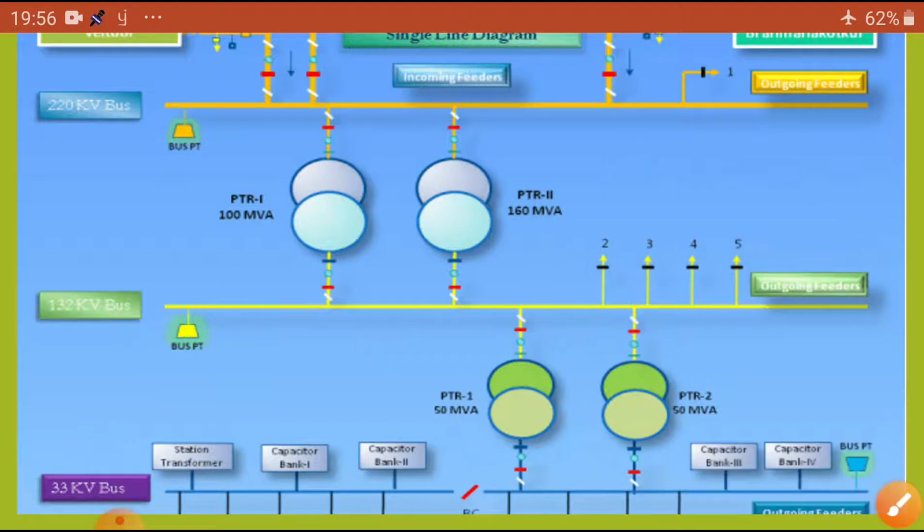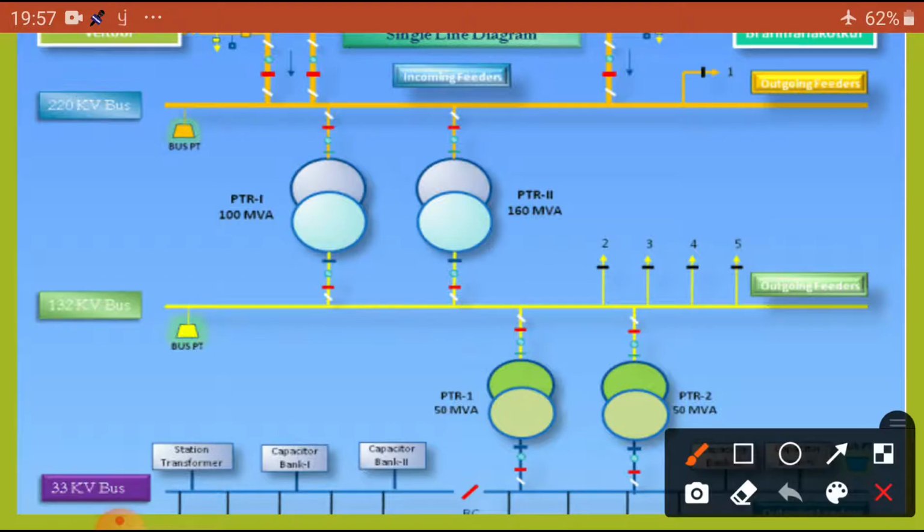So here in substations, in addition to this, on the 33 kV side we provide capacitor banks 1, 2, 3 and 4. Because if the input voltage changes plus or minus, we know, 10%, then what will happen? We are going to switch on the capacitor banks to meet the load and generate the reactive power. That's why generally 5 MVA or 15 MVA capacitor banks are provided here.